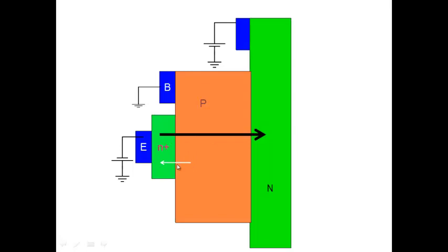And this is a current which is independent, which is fine. Okay, so now in this particular situation, if we define collector current here, let's call this current IN, the electron current component, and let's call this IP. So collector current will be equal to IN, because there's no other current. Note that this is reverse bias and the current of this particular junction is very small. By itself, the intrinsic current is very small. It's a reverse bias junction. The current that comes in from here is the important current here. So IC is basically equal to IN.